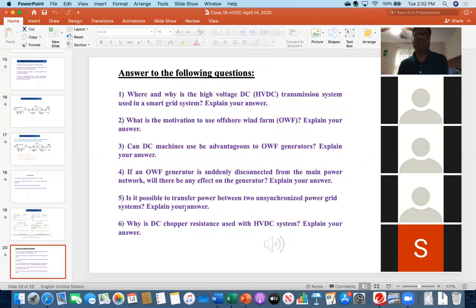So now everybody see, the question was number 5. Is it possible to transfer power between two unsynchronized power grid systems? The answer is yes. When I am explaining how, with the help of the HVDC system, because the DC system is independent of frequency.